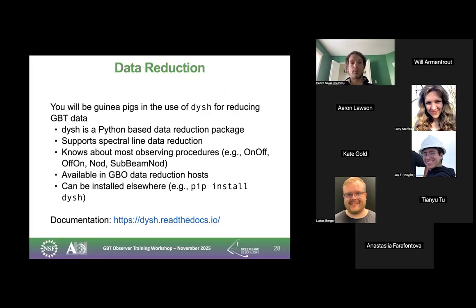And one more, the last part of this talk is going to deal with data reduction. So basically, we saw the theory, right? This is the power that's coming in. This is the model we're using, where the power is equal to the gain times the antenna temperature plus the system temperature, right? Measure an on and off. We subtract one from the other, I mean, a signal and a reference, divide by the reference, and multiply by the system temperature, right?